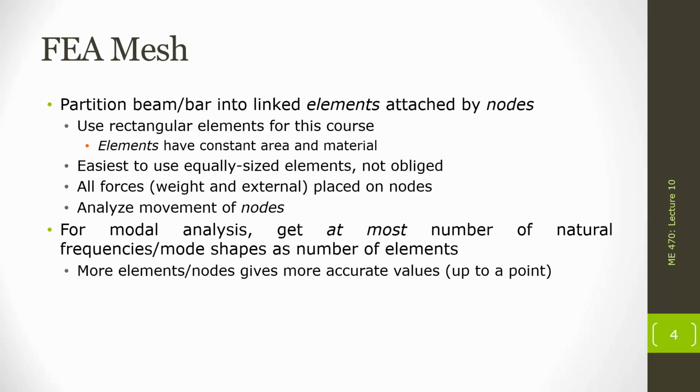So as we add a finer and finer mesh, we get more and more of these natural frequencies. What's going to happen is actually the frequencies we gain are going to always be in order from the lowest to the highest. So if we only have 2 degrees of freedom that we split our shape into, we are going to be finding the first 2 natural frequencies. However, their precision and their accuracy are going to start off very poor.